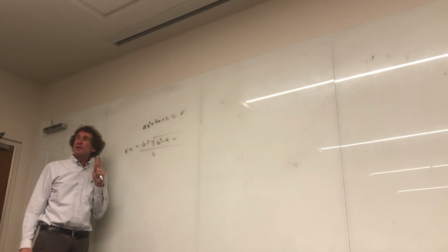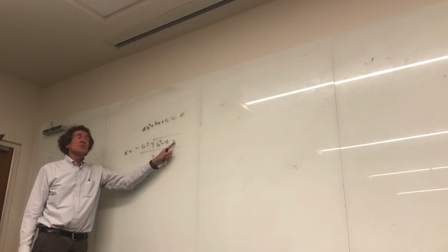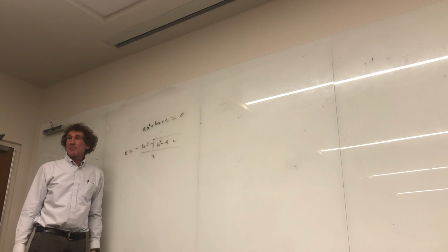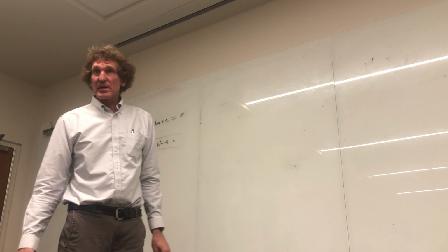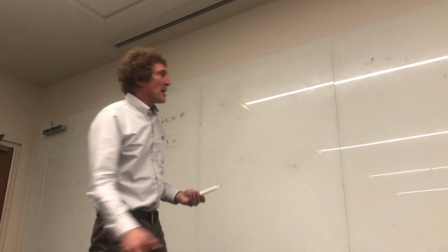All right? Now, since all the time the highest power, the s squared term, always has a coefficient of 1, a is 1. So it becomes that. I always make the coefficient of the highest power 1. And that's the roots of the equation. That's for any of them. They can be complex, there can be two real, or it can be a double, right? Because if this term is 0, then you got a double pole, something where you basically have s plus a squared. Follow me, class?